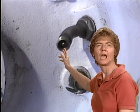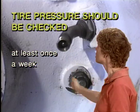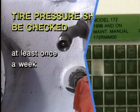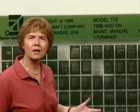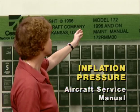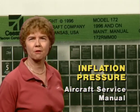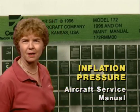Now, as far as the tires themselves are concerned, tire pressure should be checked at least once a week, probably more often, but at least once a week, the FAA says. So where do you find the correct inflation pressure for an aircraft tire? Well, you get it from the Aircraft Service Manual. You do not get it from the manufacturer of the tire because the inflation pressure will vary from aircraft to aircraft, even for the same tire.